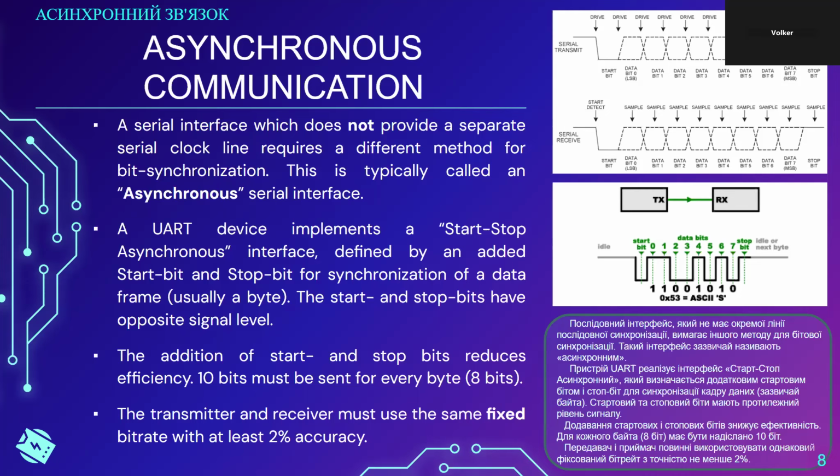My recommendation, if you're starting to design a system that needs to connect over UART, RS-485, or RS-232 interfaces, and you are trying to use the internal RC oscillator, is to read very accurately in the datasheet how accurate this RC oscillator actually is at the temperature extremes, at -40 degrees, at +85 degrees.